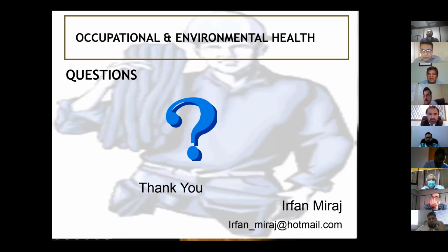The basic indoor air quality, which we talked about last time, is those 4 parameters: carbon dioxide, carbon monoxide, temperature, and humidity. That controls 90% of the complaints.